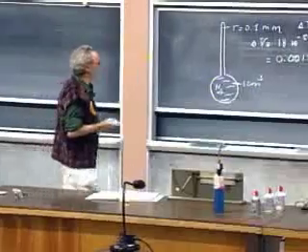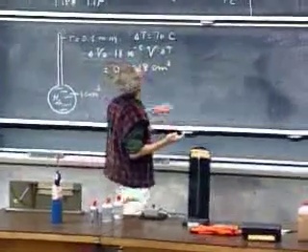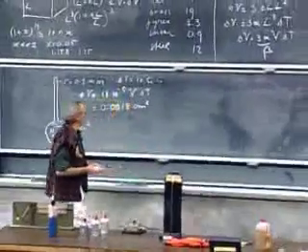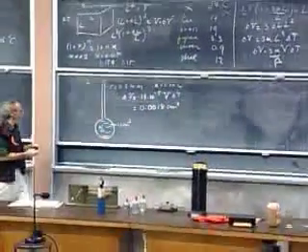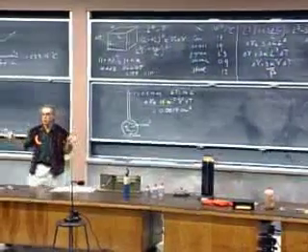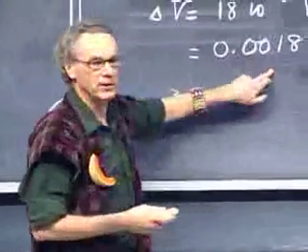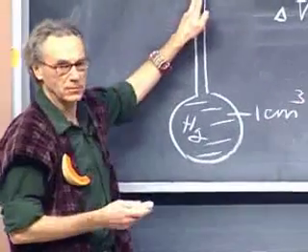However, the Pyrex is not expanding at all. You can just forget that for now. If you want to calculate how much it is, it's fine, but it is 18 times less. So the fact that this vessel gets a little larger, of course, is important, but I will just ignore that for now. And so I will just assume that all this mercury will be driven up here.